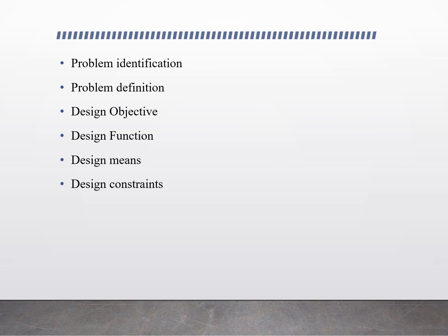After that, you need to consider the design constraints. What are the design constraints in this problem? Should it consume less space, less energy and have less weight? These are the functional constraints. And the second, operation of the machinery should be safe for the people involved. This includes the safety constraints. And the production of components, purchase of components, assembly, transport, process, etc. are to be taken care of. This includes the manufacturing constraints. It should be cost effective, which includes the economic constraints, and should save time for the persons involved, which includes the time constraints, etc.